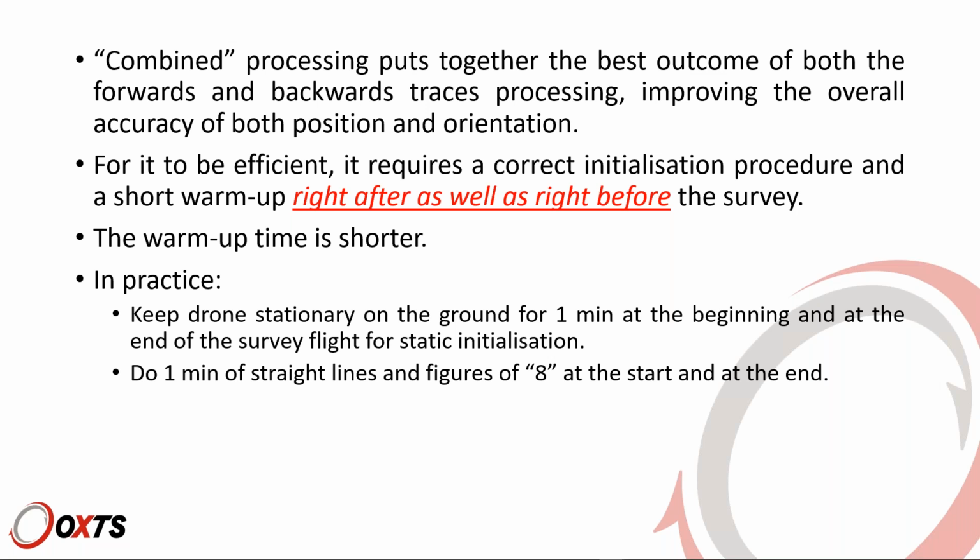Okay, this, in return, will shorten the warm-up time. As we said, if you are processing in combined mode, your warm-up time can be down to 1 minute. So in practice, what does it mean? It means that after you are done with your survey, you need to do a minute or so of straight lines and figures of 8. That is the warm-up for the backwards trace, and then stay stationary on the ground for about a minute. That is the static initialization time for the backwards trace.